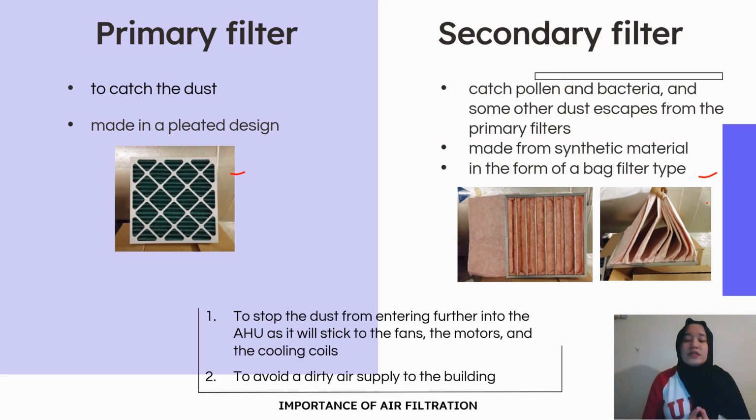So the importance of air filtration is, first, to stop the dust from entering further into the AHU, as it will stick to the fans, the motors, and the cooling coils. Second is to avoid a dirty air supply to the building.